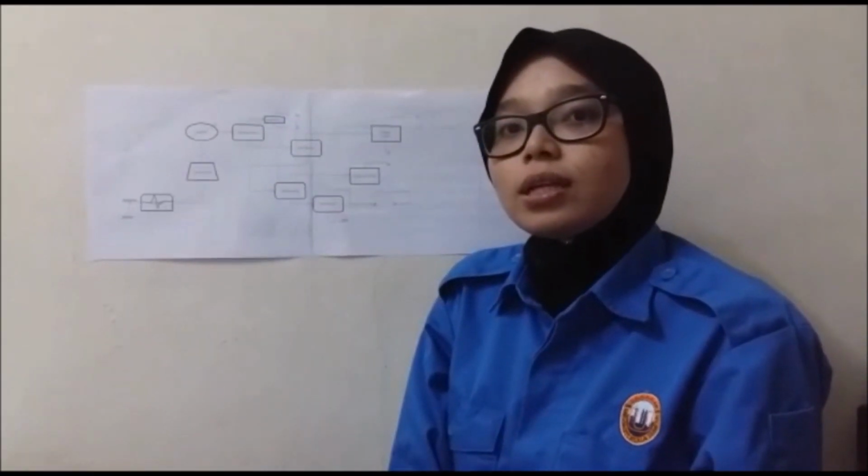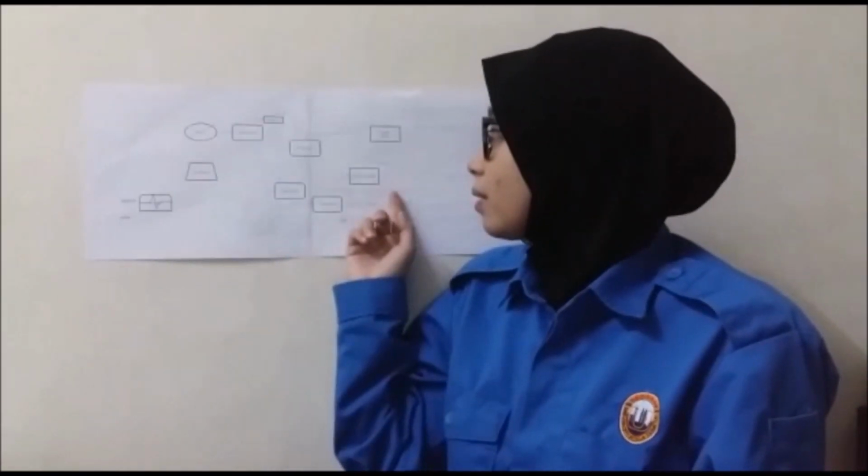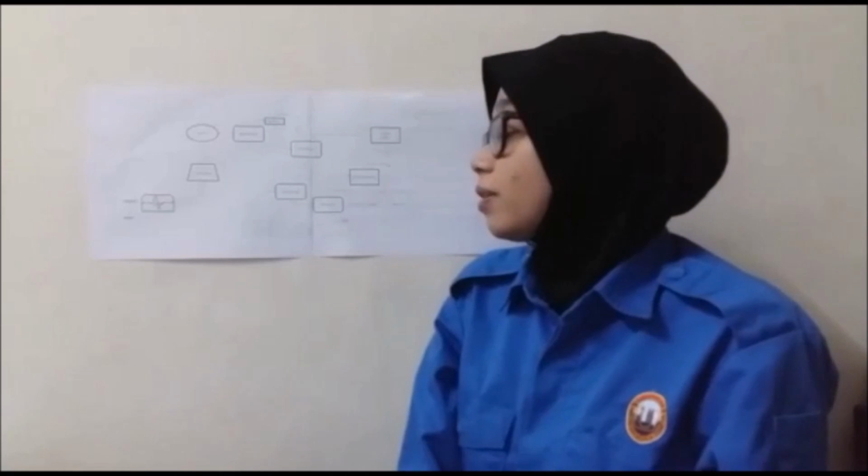The propylene splitter is used in the naphtha cracking plant. The function is to separate propane and propylene. In this process, we make sure that the overhead stream will have at least 95% of the propylene and the rest with the propane.